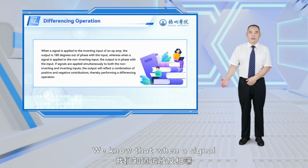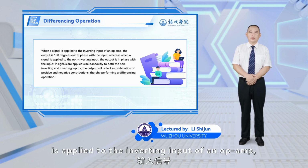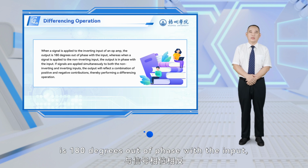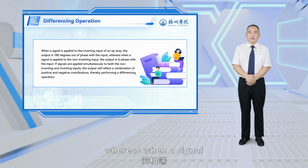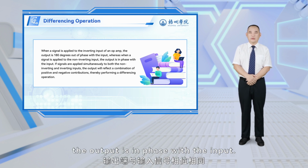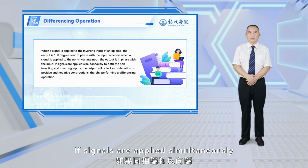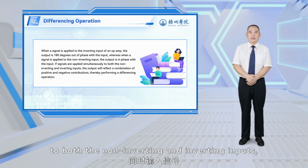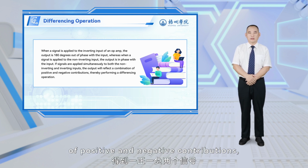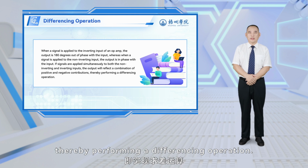We know that when a signal is applied to the inverting input of an op-amp, the output is 180 degrees out of phase with the input, whereas when a signal is applied to the non-inverting input, the output is in phase with the input. If signals are applied simultaneously to both the non-inverting and inverting inputs, the output will reflect a combination of positive and negative contributions, thereby performing a differencing operation.